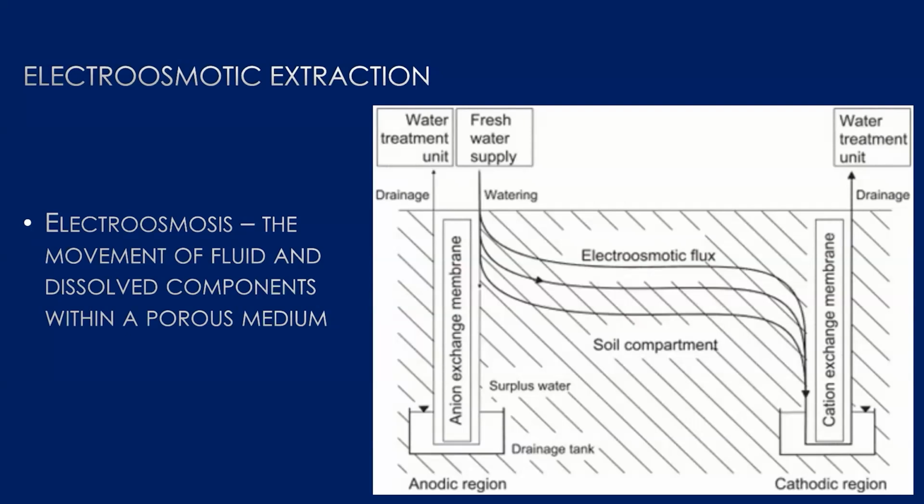So, when the electric field is applied, these positively charged water molecules will move towards the negatively charged cathode. As the cations move through the porous medium at a relatively high velocity, a shearing action occurs as they pull the water molecules towards the cathode. So, over time, enough water will be pulled towards the cathode that the system would cease to accomplish its goal because the anions in the porous medium that are moving the opposite direction of the water would run out of water to move through before making it to the anode. Additionally, cations that happen to start close to the anode might be left behind if the water moves away quickly to the cathode.